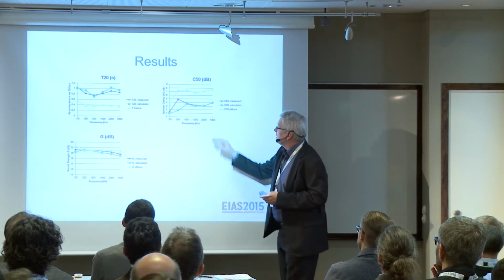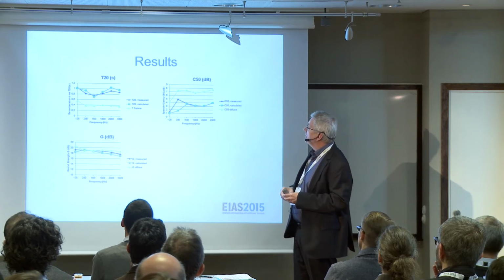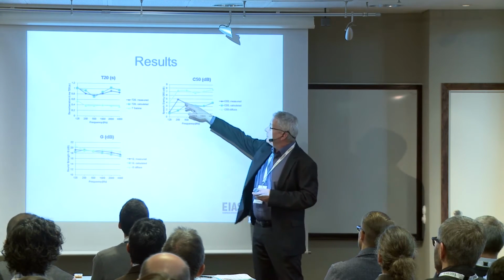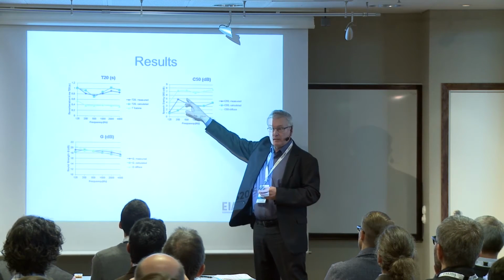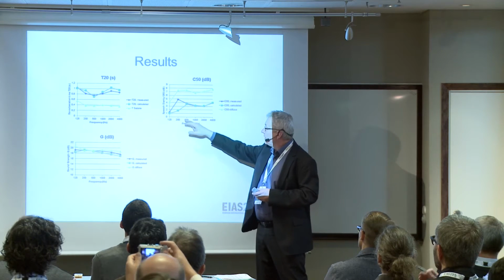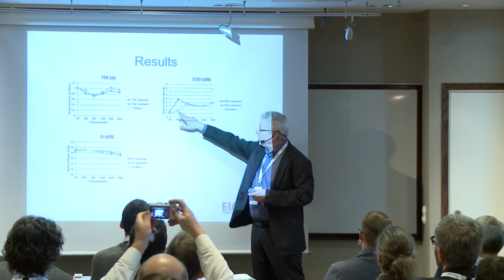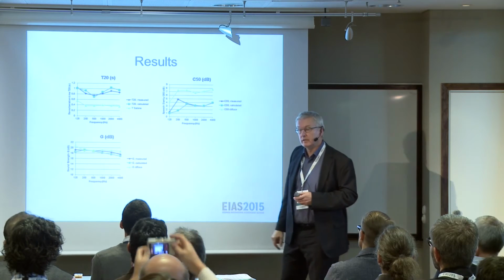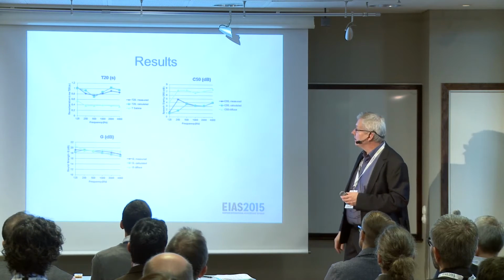And if we look at the C50, then we also see that the diffuse field theory really overestimates the C50. But here we got quite a good correspondence. I don't know what happens with 250 Hertz, but there are some differences.